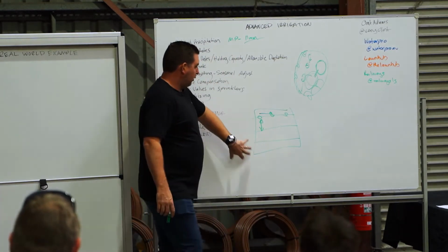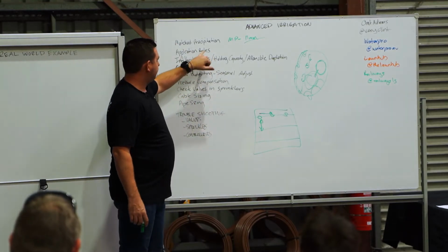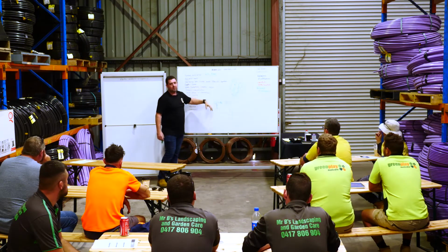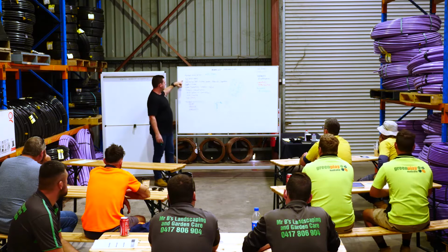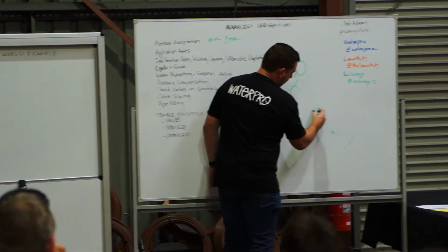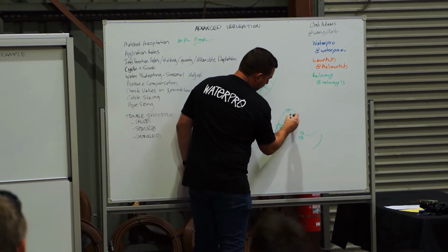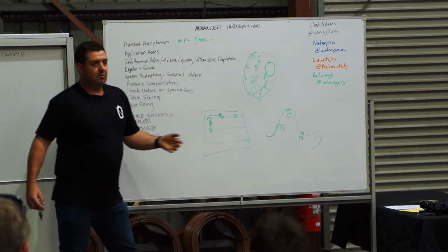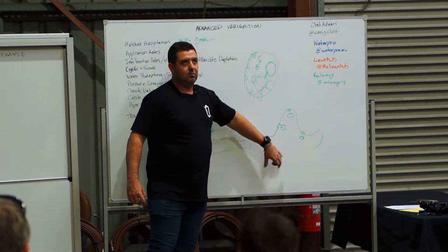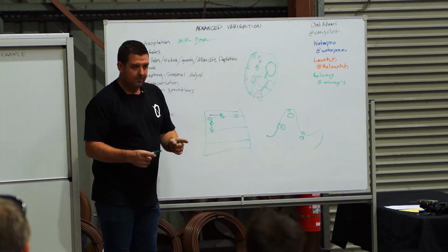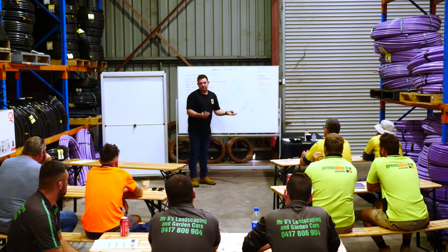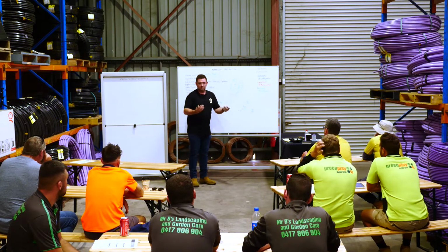So if you're gridding like this, you will have the ability to actually calculate your application rate, which might be 17 mil an hour, it might be 25 mil an hour, and that obviously helps you when you're trying to work out your application further. If you just snake your drip tube around and there's just a dripper wherever, and there's a tree there, and a tree there, the scheduling is going to be different. You'd probably move down the path of going, well, there's two drippers either side of that tree, and they both put out 1.6 litres an hour. That tree needs 10 litres a week, so we'll reverse engineer that to make sure that we're watering for the right amount of time.